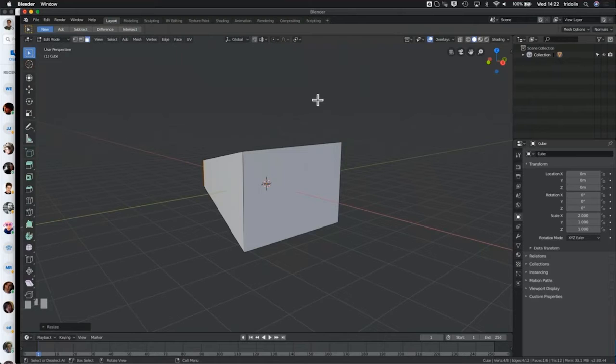You can merge vertices. So if I go into vertex select mode, again, right up at the top left of the screen, in edit mode, and I click on the two vertices I wish to merge, or more, doesn't have to be two. Remember, you can select multiple with the Shift key, and then if I press Alt-M, that's the control for merging vertices, or edges, or faces. Is it somewhere in the menu as well? Yes, it is. And it's also in the cheat sheet of keyboard shortcuts that I gave you, because I do think it's a useful one. It should be in there. And then you get this contextual menu appear where you can say where you wish to merge them. You could merge them at the center to get that kind of effect.